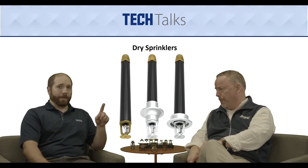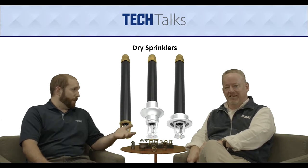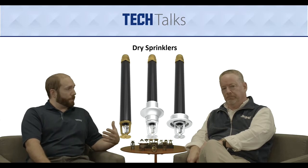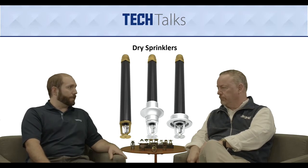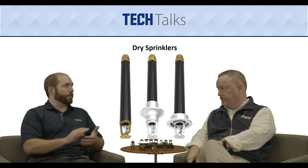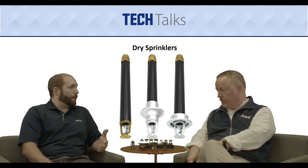Yeah, and I'll try my hand at pointing. So the drop right here, that's the barrel of the sprinkler for our dry barrel sprinkler. It actually has a special coating to it. We call it an E-coat, an electro-deposited epoxy-based finish. That is what we apply to a steel pipe to give it its corrosion resistance. So there is some corrosion protection to the drop as well.